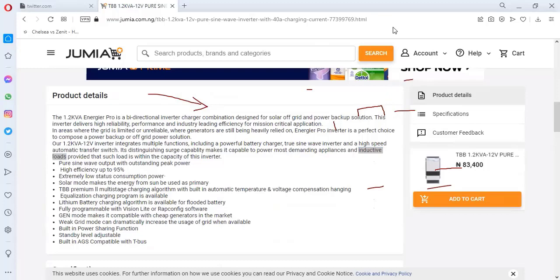Sir, the power factor, does it come with the power factor? Okay, so now the power factor in your design calculation, sometimes you need to look at the inverter manual. You can find the power factor in the manual. So maybe you want to design for an inverter, then look at the manual, look at the power factor. So you can say, okay, let me use this in designing. You've gotten the inverter manual, so that means you are using that inverter to design.